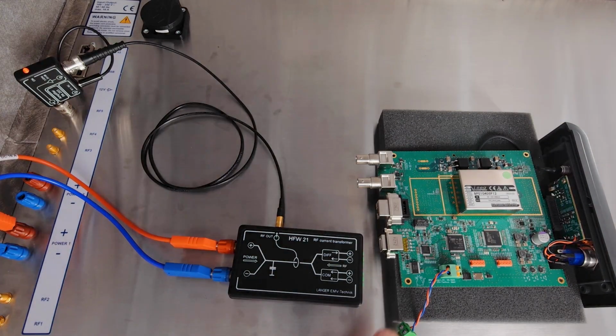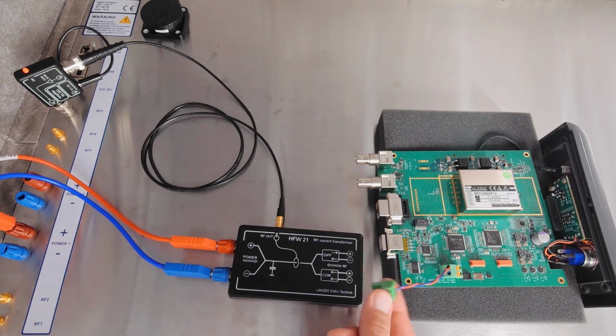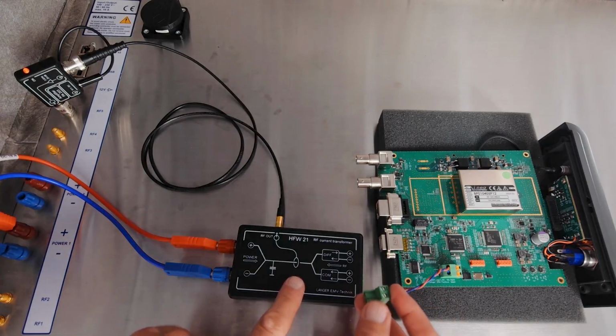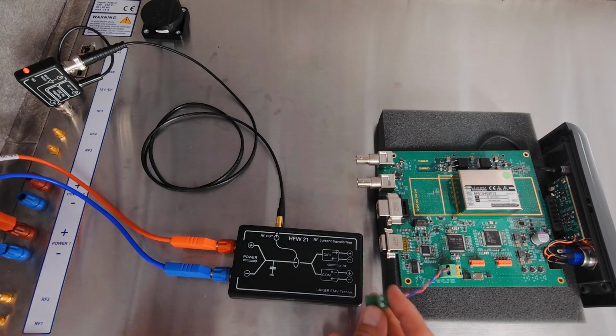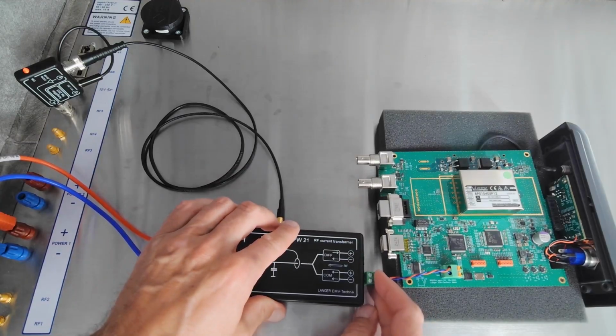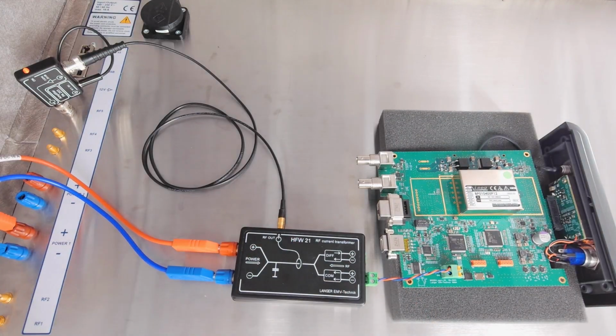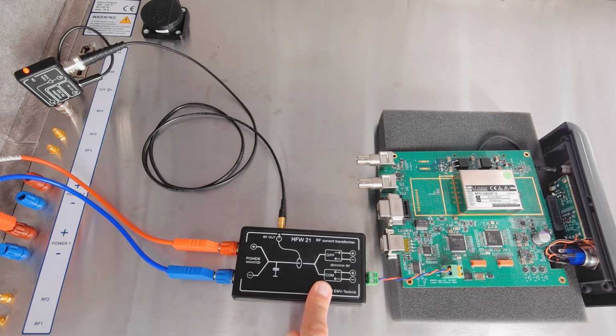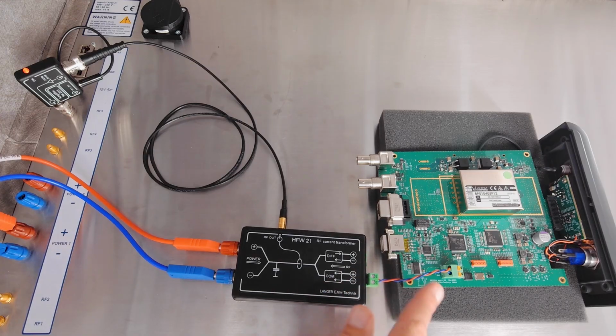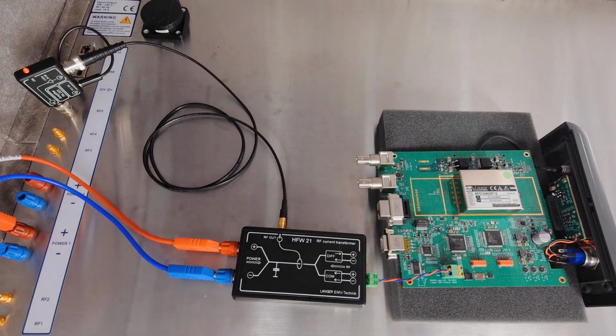And here you can see for the power supply of this electronic device, I prepared here a short cable with a connector for our RF current transformer. And here now we have the possibility to connect this power supply cable to our RF current transformer. And here I used the common mode connection for RF common modes, because I want to measure this device, or this device has a problem in the higher frequency range. And for radiated emission, most of the RF currents are coupling into the cables as a common mode current.